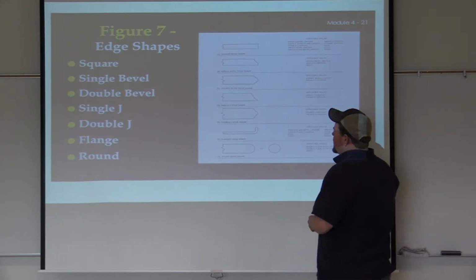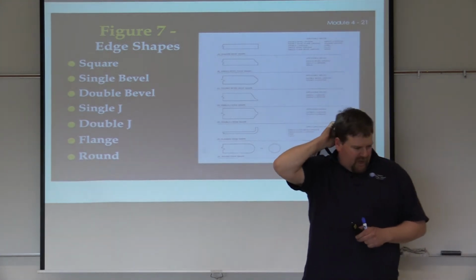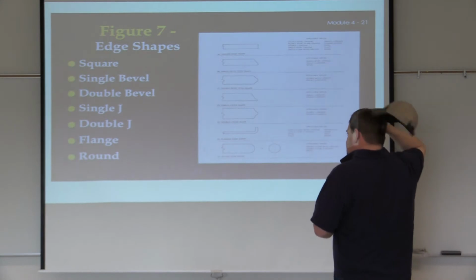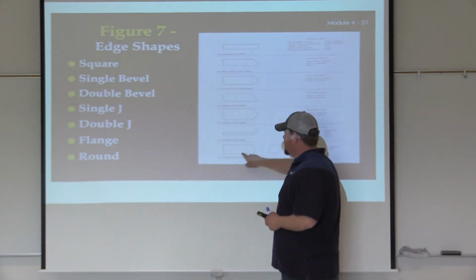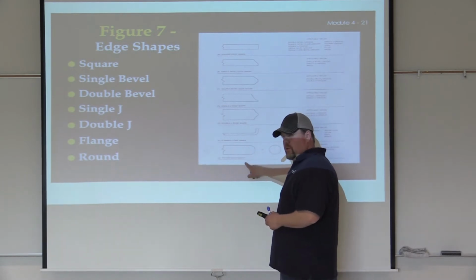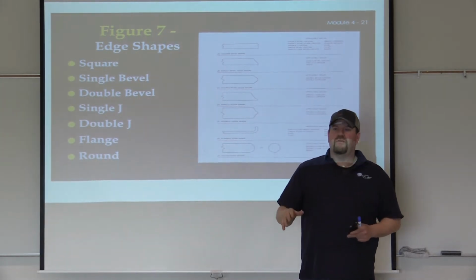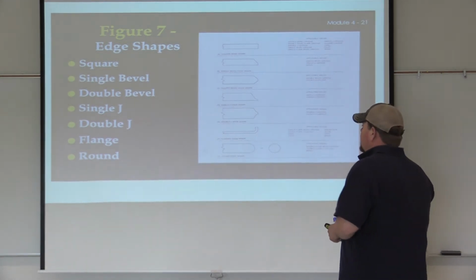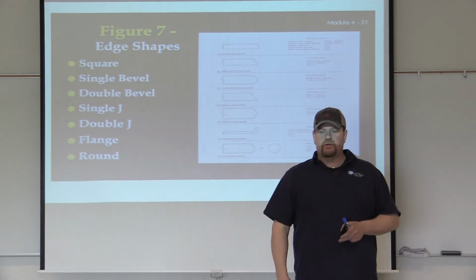One thing I want you to think about is round is a lot of times we're dealing with thicker plate, right? It's important to know that your rolled plate usually comes with a conical surface as well, a rounded edge. So if you put that up against the surface, just a brand new side of plate, sometimes I've had it where they required me to cut that first half-inch off where it was a good 90-degree straight edge.